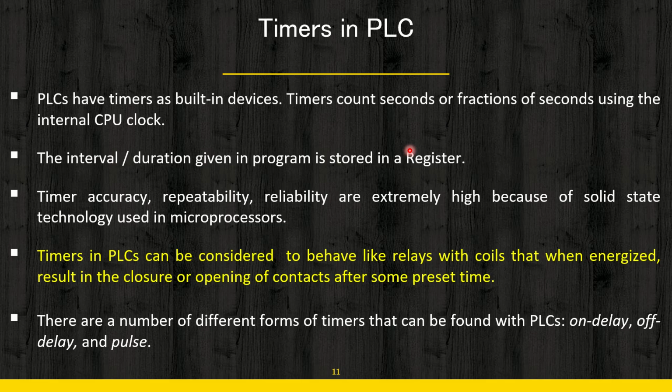Now there are a number of different forms of timers that can be found with the PLC. You can have an on delay timer, you can have an off delay timer, you can make it work like an interval timer, and definitely you have got a pulse timer. So all these things are there. And at the same time, I will repeat again and again that all the manufacturers, they have got different format of timers. Different methods are adapted in the ladder language to program the timers. So unless you go into each and every of them, you cannot understand operation of timers in each and every